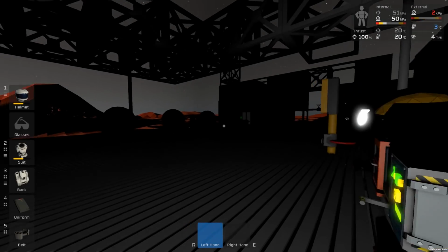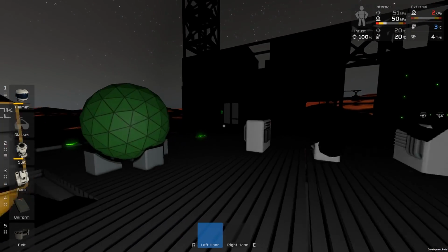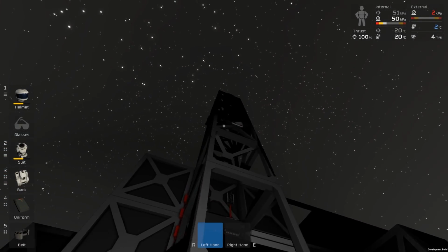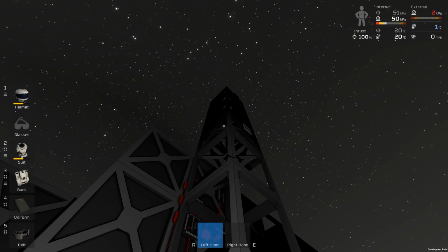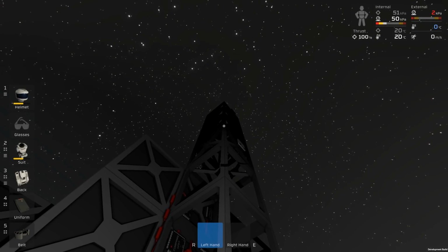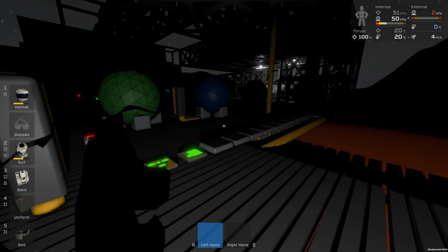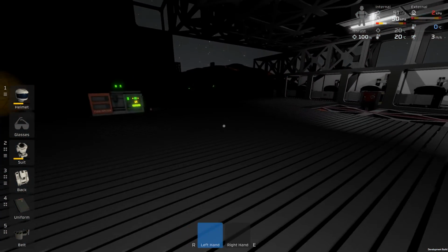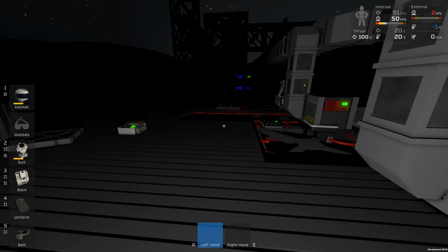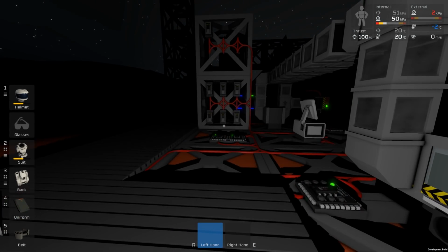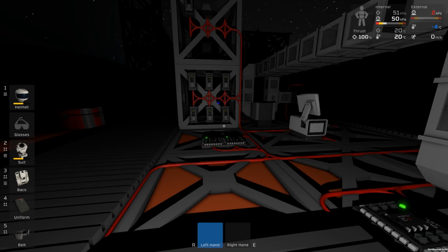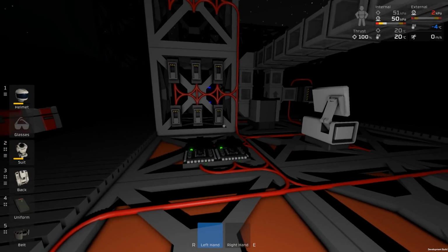The trouble with Mars, and you can't really do this one on Europa. We'll have more Europa episodes to come fairly soon, but you can't really do this on Europa. On Mars, you have this day-night cycle where the temperature goes from -70 up to +20. When it's at +20, that's a lot of really nice gas we can use to extract the heat from. However, we can't just put it through typical extraction of heat like an air conditioner, because it needs a certain amount of pressure to do that, and we don't have the pressure of the atmosphere. Pressure is only 2 kPa. We need a few times that to actually get the heat out of it, at least.